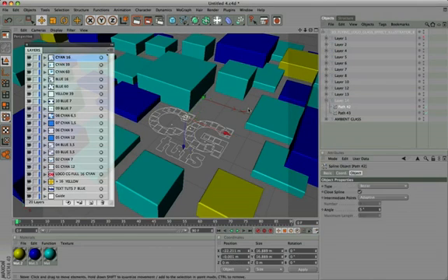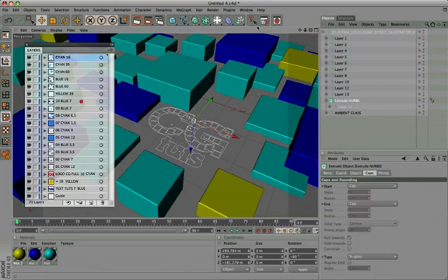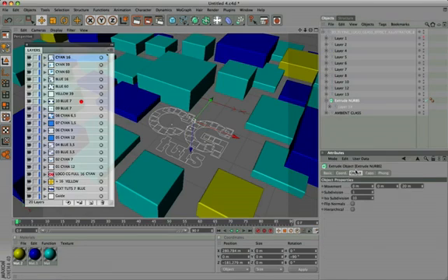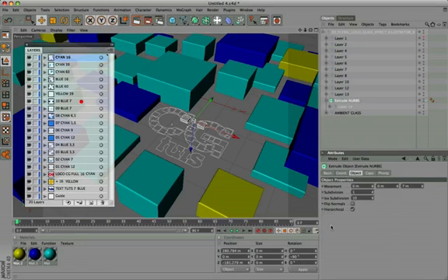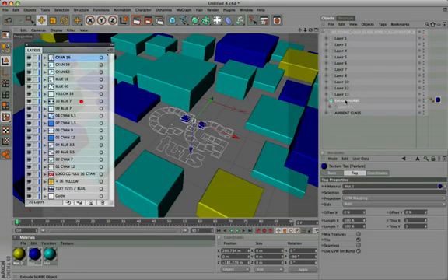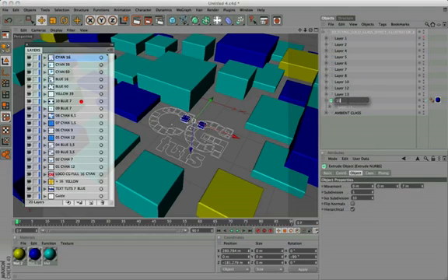We continue with the cubes that make up the mosaic logo. Select layer 14, and holding the Alt key, apply the Extrude tool. We apply the value 7, and check Hierarchical. We apply fillet caps at the end, step 6, radius 0.85. Apply the blue material, and rename it 10 Blue 7.